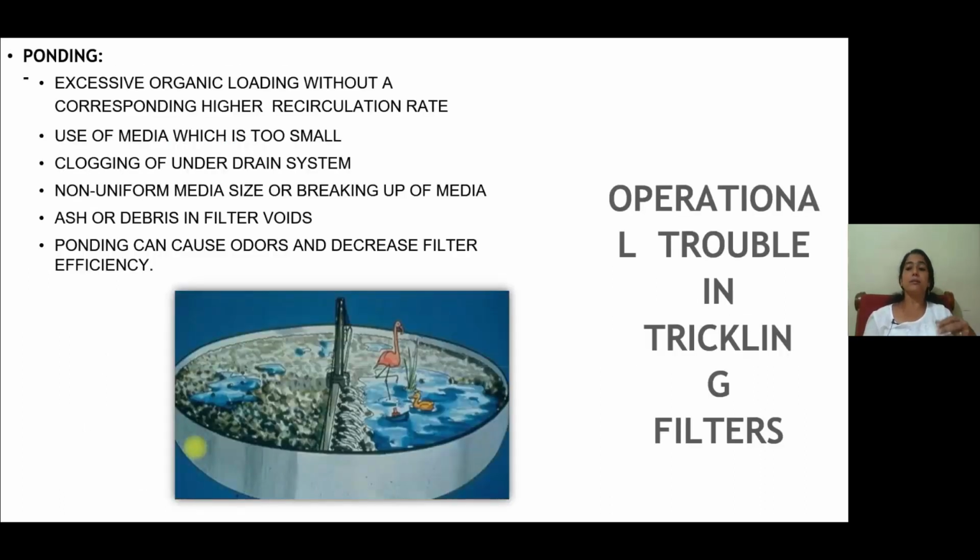Then the operational troubles in trickling filters. There are so many operational problems related to these trickling filters, but the trickling filters are commonly used in wastewater treatment plants as the filtration system. Excessive organic loading rate without a corresponding higher recirculation rate.